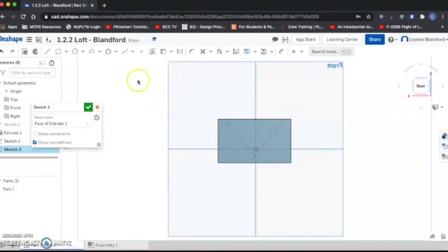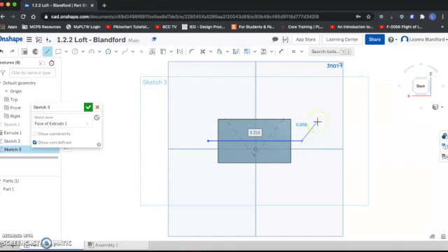So I'm going to start with my construction lines again. So I'm going to grab my line tool and draw a horizontal line across my rectangular prism and hit my escape key. I'm going to turn this line by highlighting it into a construction line with my construction option. And then I'm going to dimension it so that it is 0.75 inches from the bottom edge. And I'm super close to that already. It's barely going to move.